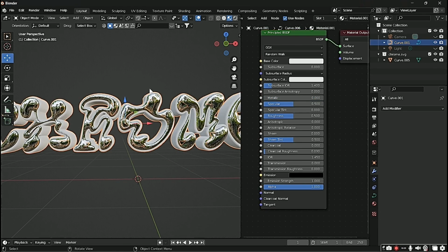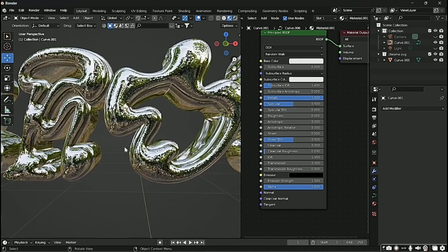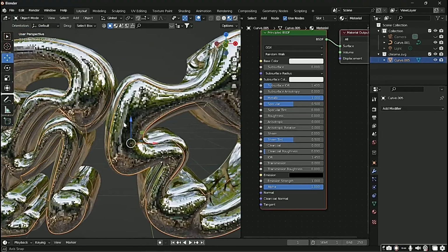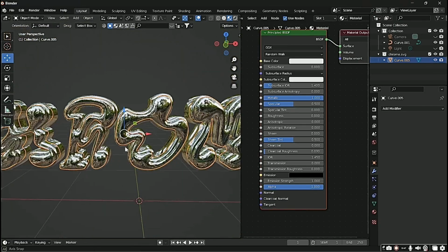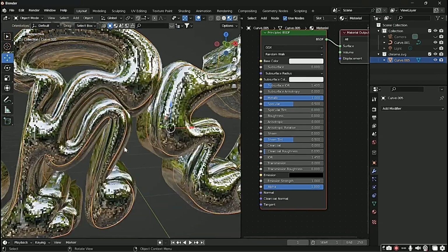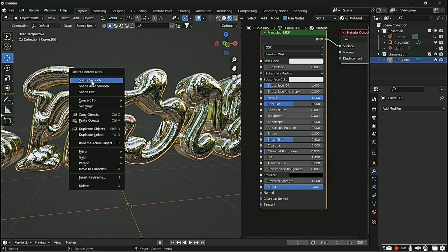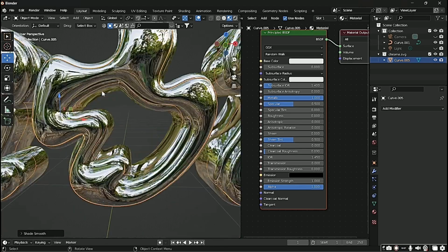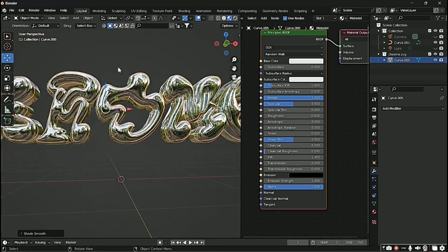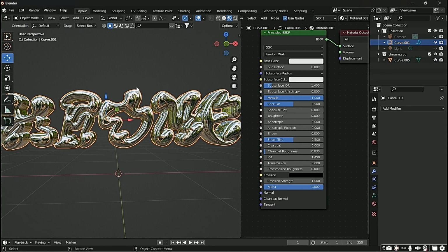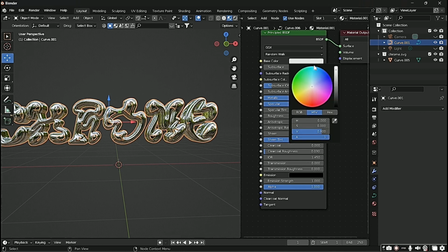And then we're just going to do the same thing with the outline. If you scroll in, your object that you sculpted might be very pixelated. That's very normal, but the way to fix this is by right clicking and you press shade smooth, and as you can see, it smoothed out the pixels. And I want my outline to be slightly darker than my actual object, so I can just adjust the color up here.